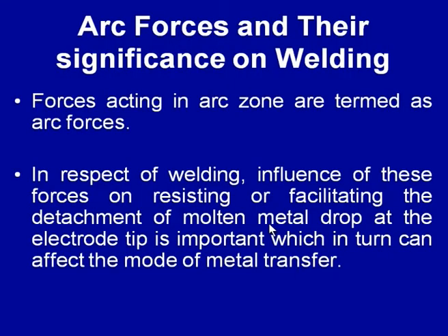So, depending upon the type of arc forces present and their magnitudes, the metal transfer is mainly affected, and sometimes apart from the metal transfer, the spattering is also affected by the arc forces generated in the arc region. In this lecture, we will see what the different arc forces present in the arc zone are and how they affect the metal transfer and the spattering aspects in the process of developing a sound weld joint.